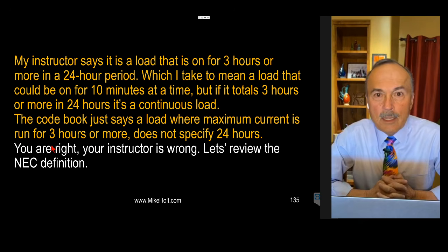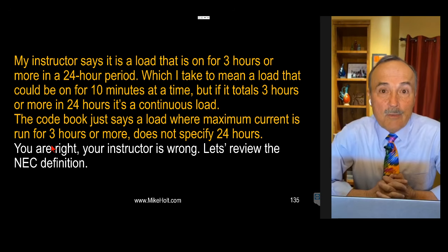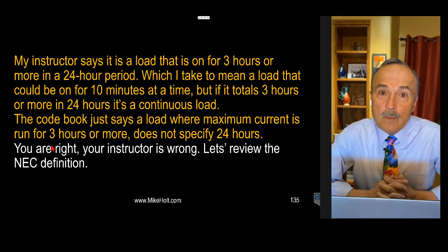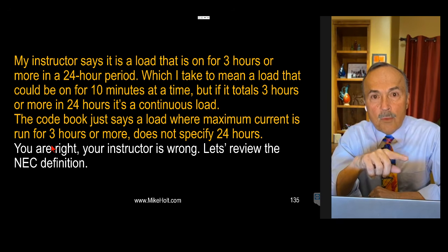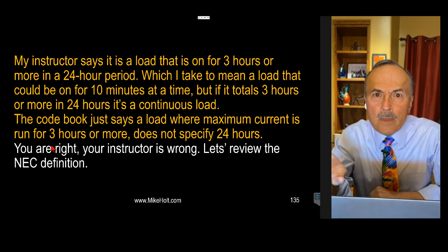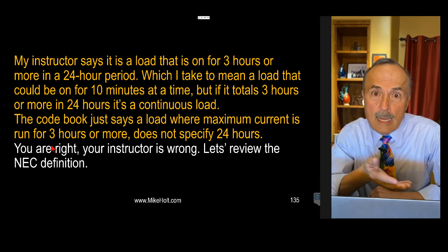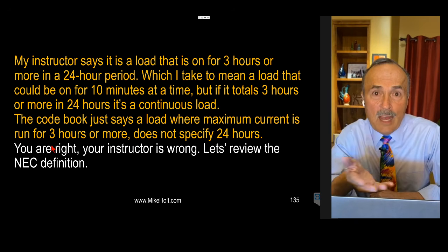Mike, come on, man. Every single commercial, industrial job, not residential, but pretty much all the loads are continuous. Right. Well, that doesn't make any sense. Well, that's the way it is. So now what does that mean? That means that you have to limit the load on the breaker to 80% of the rating of the breaker so that you can use the breaker. And is that stupid? You would think that if it says 100 amps, you can put 100 amps on it, whether it's for 5 minutes or whether it's for 5 hours.